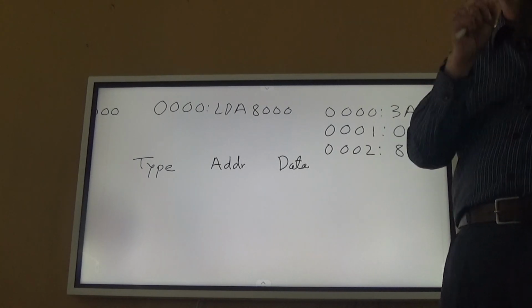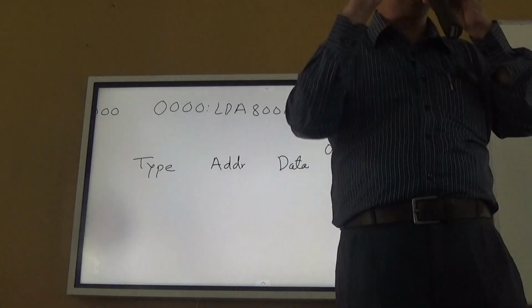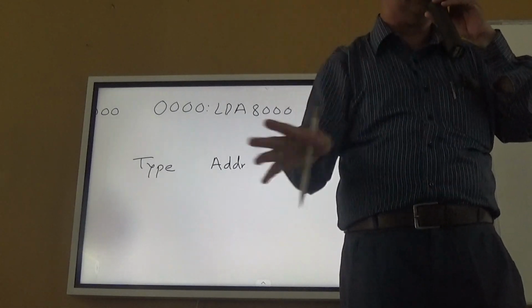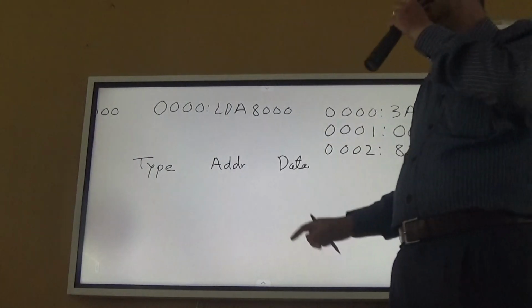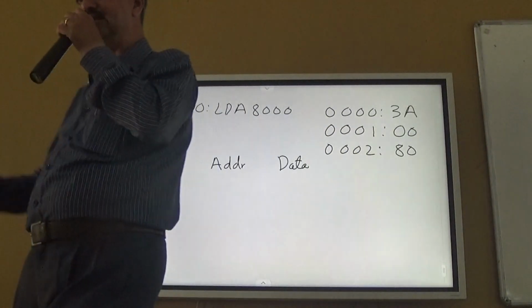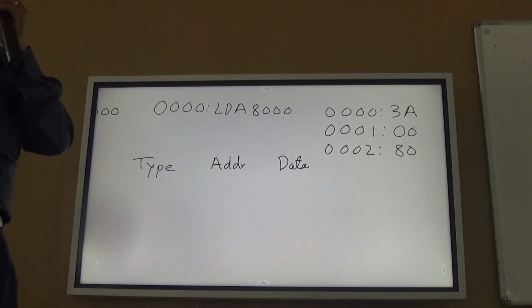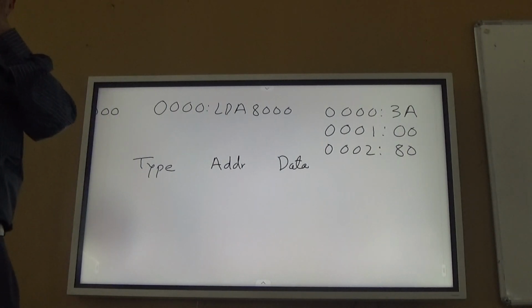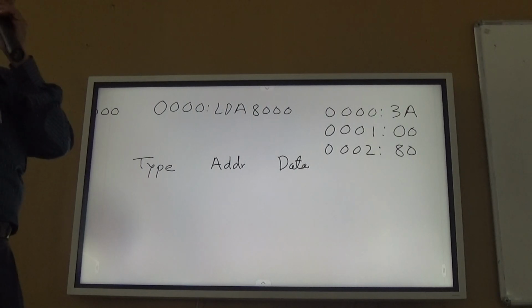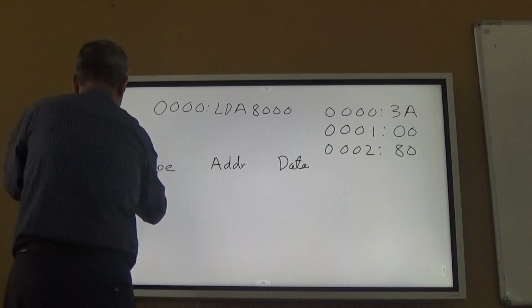For each machine cycle, one of the 16-bit register pairs must give the address. And for each machine cycle, if it is a read cycle, data must go into one of the 8-bit registers, and if it is a write cycle, one of the 8-bit registers should give the data. So, after reset, what cycle should it be? Opcode fetch. We say that fetch F.